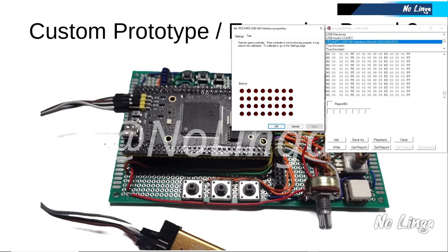So if I turn the encoder down, the second bit will light as a button. And in the cockpit, I'll show you how I map these. And if I turn it up, the lower bit will map. So each encoder channel is mapped to a pair of bits. The second encoder on the lower knob, when you turn it down, shows the upper bit. And when you go up, it shows the lower bit. So each encoder is also attached to 2 pins. And you can see on the screen also the USB SimpleHID values being triggered.